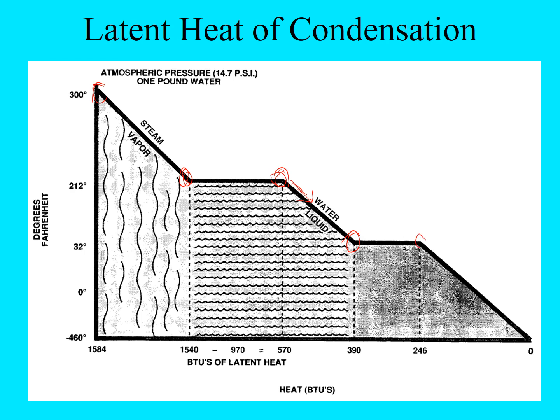And once we get to this point, we would have our pound of ice again. And then we can cool it even further and make that solid colder. But this is the latent heat of condensation. So when we change the state of a vapor completely into a liquid, that's when we have the biggest heat transfer taking place. And vice versa, when we go from a liquid to steam, that's also where we have the biggest transfer of heat taking place in both of those events.